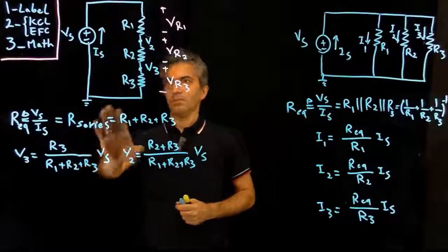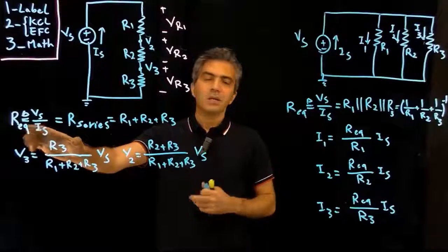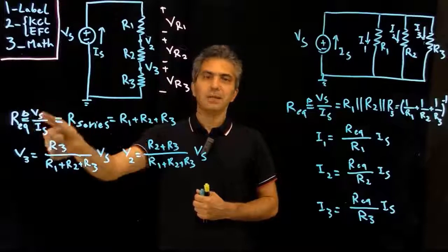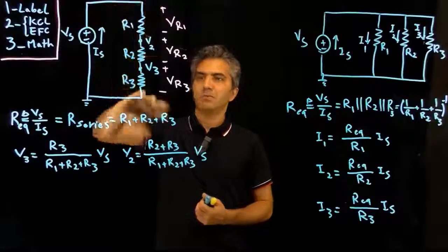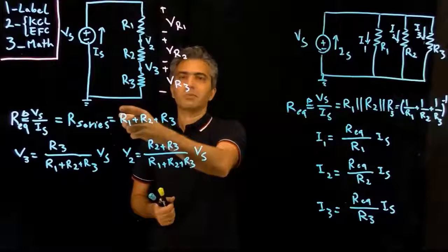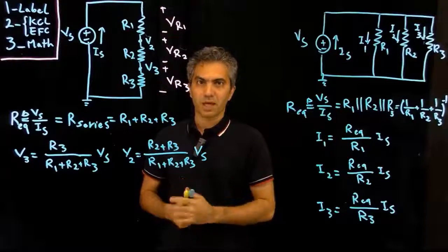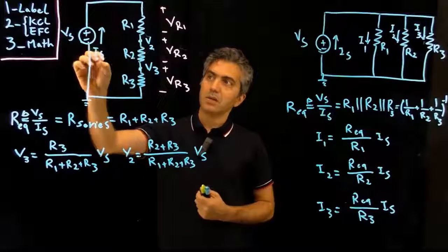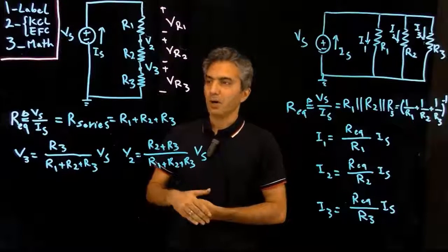So we looked at the situation, and then we defined the equivalent resistance, which is a completely universal definition, and basically it's the definition of resistance. We said if we have a box with a bunch of components, and in this case the components are in series to each other, but generally speaking with two terminals coming off of it, if I connect a voltage across those two terminals and then look at the current that is going into that, assuming that that's the only source of energy that I connect to that box, then the result would be the equivalent resistance of that box.